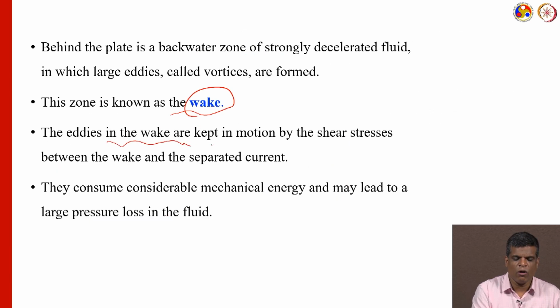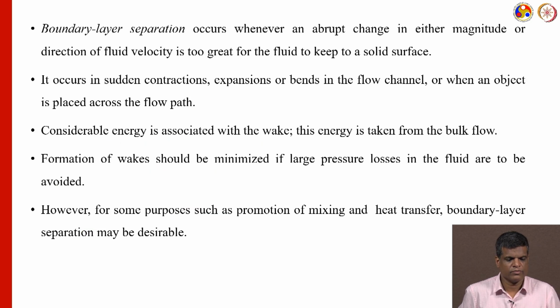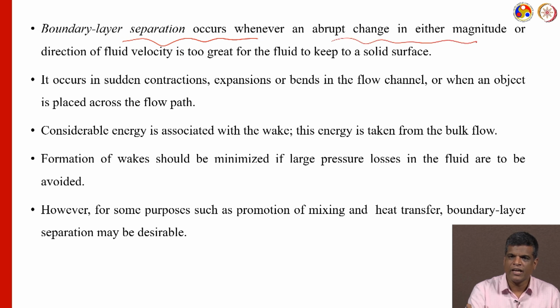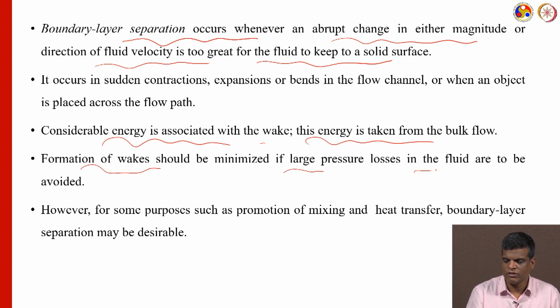Eddies in the wake are kept in motion because of the shear stress between the wake and the separated current. They consume considerable mechanical energy and may lead to a large pressure loss in the fluid at that place. The boundary layer separation occurs with abrupt changes in either the magnitude or the direction of fluid velocity near the solid surface. The considerable energy associated with a wake is taken from the bulk flow. The formation of wakes should be minimized if large pressure losses in the fluid are to be avoided.